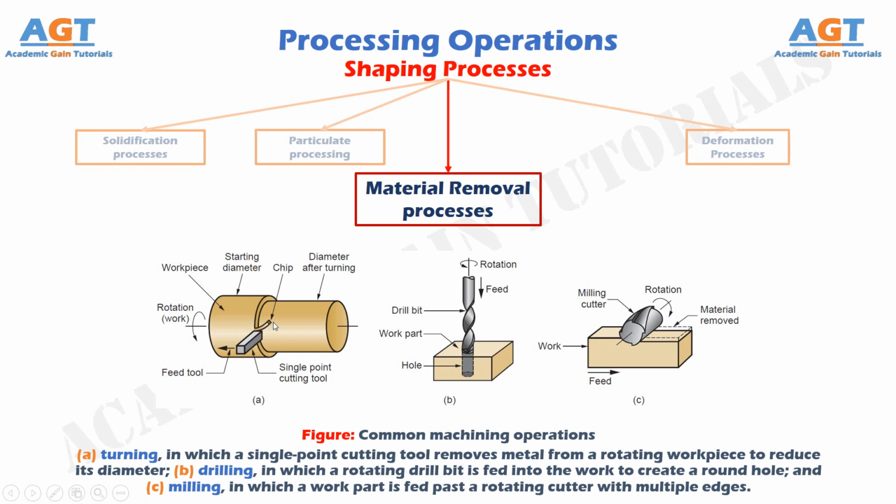Other processes, such as certain casting and molding operations, often convert close to 100% of the starting material into final product. Manufacturing processes that transform nearly all of the starting material into product and require no subsequent machining to achieve final part geometry are called net shape processes. Other processes require minimum machining to produce the final shape and are called near net shape processes.